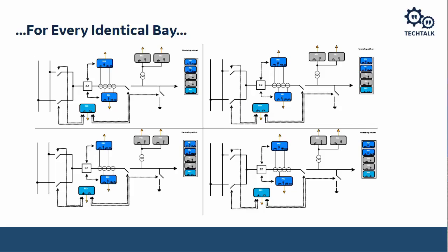The options that we have available for sizing, you can do a direct connection, so no switch networks. We can handle up to 8 merging units. If you need more than 8 merging units, we can go into a switch network, which can take you up into larger numbers. For a bus protection, we can go up to 24 circuits. So lots and lots of possibilities.